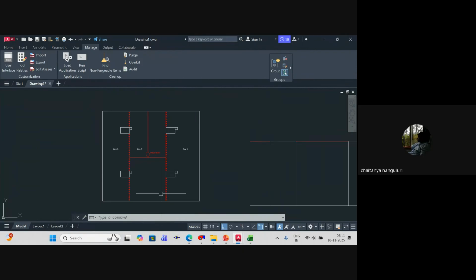When you have this deluge system, the pipe sizing is simple. You can consider 6 FPS or 8 FPS velocity and a friction factor not exceeding 4 feet per 100 feet, and then do your pipe sizing. You guys are already plumbing consultants, so I don't need to teach you pipe sizing specifically. And you'll select your pump head calculations for this. I'm skipping pump head calculations directly. I guess that should be fine for you guys, right? You're already aware of pump head calculations.